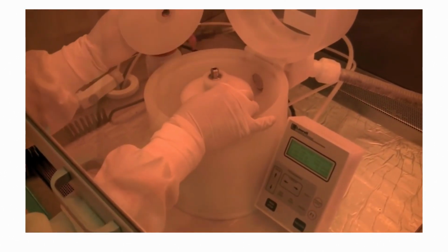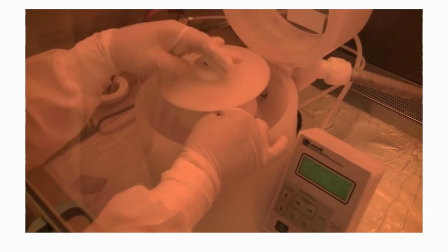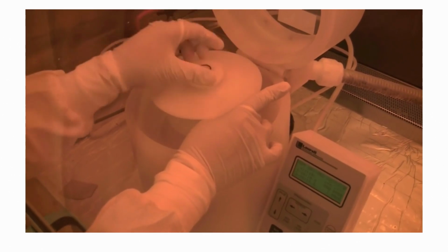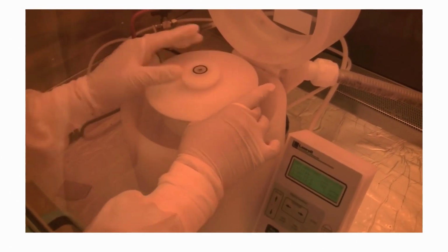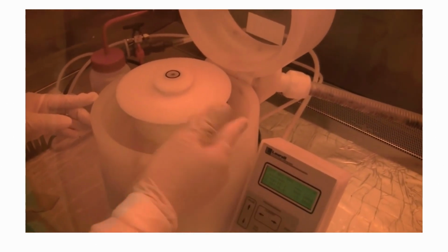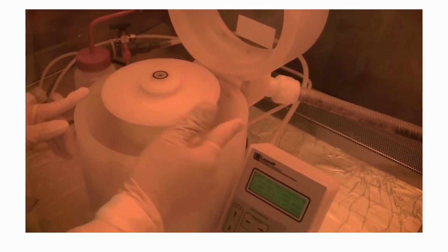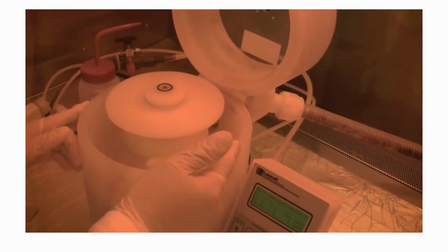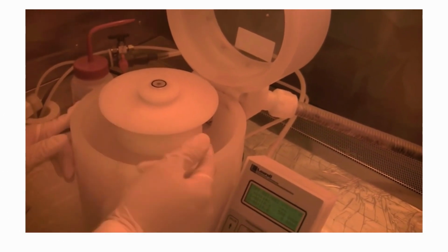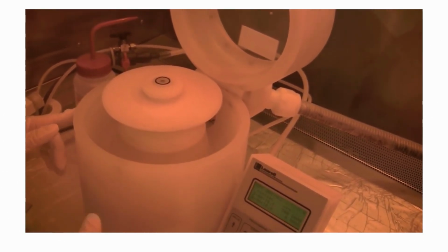When it's done, you put it on the same way. You hold this little stick here, and you see the screw, just screw it back in. When it's in good condition, you should be able to spin it freely. So see how I give it a little bit of push and it spins? Right now it's not so great, it's a little dirty. You want to see it do 2 revolutions at least. Right now it's doing maybe 1. So it's almost due for a good cleaning.